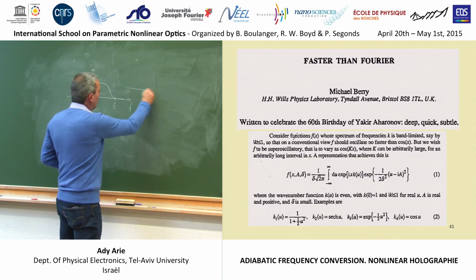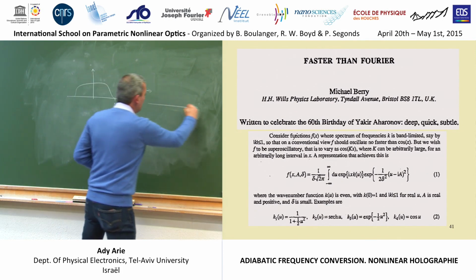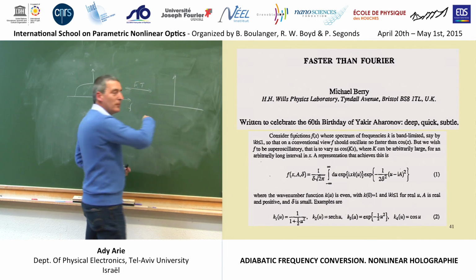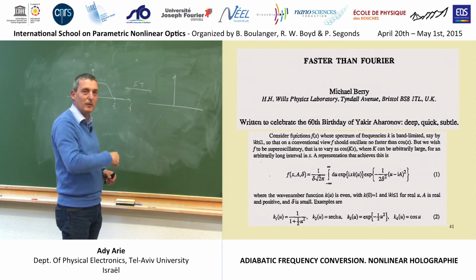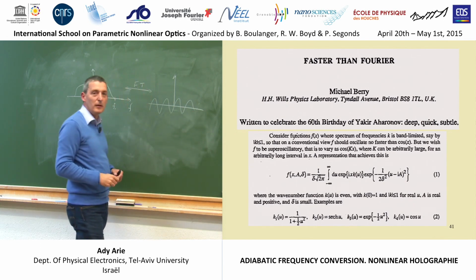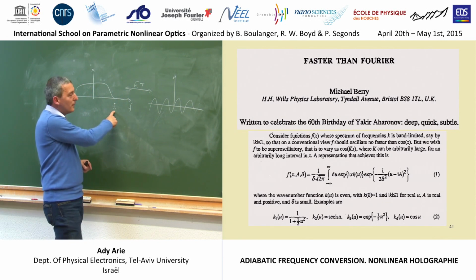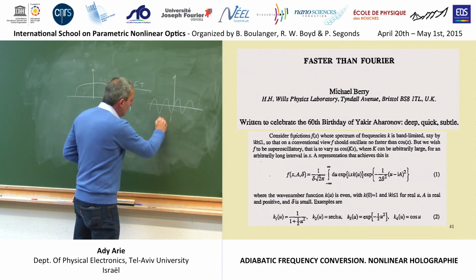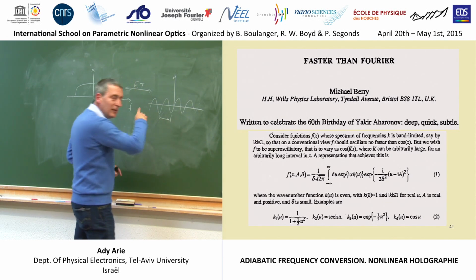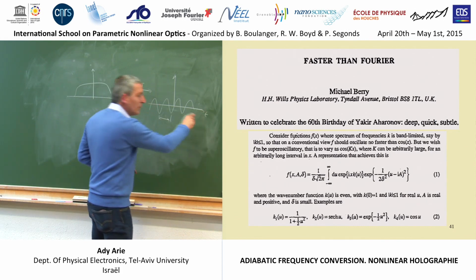And now I do a Fourier transform, so I can get it as a function of space or time, depending on. So I will get something here. Now, if this is the maximum frequency, f0, then the question is: what is the fastest rate that this function can change as a function of time?